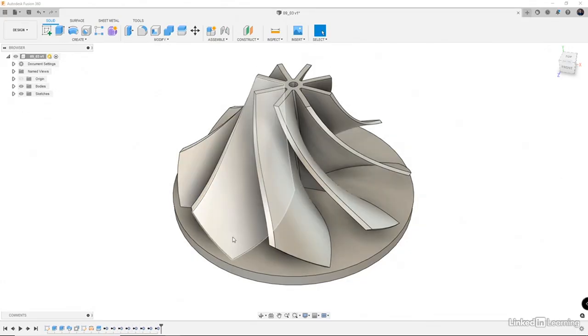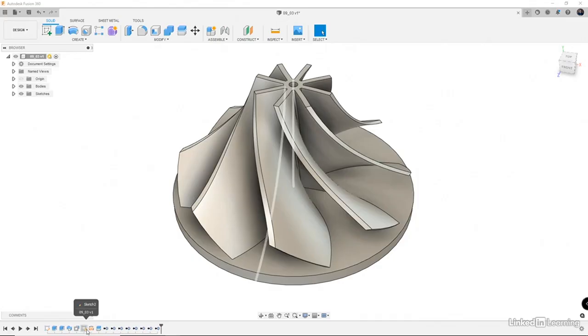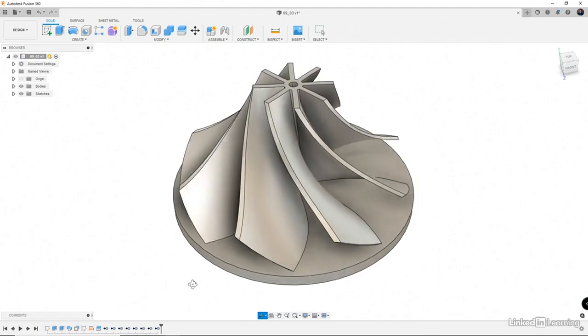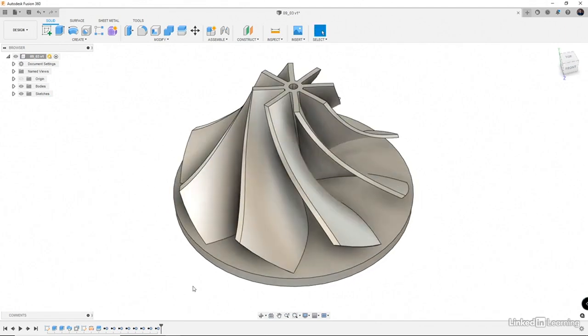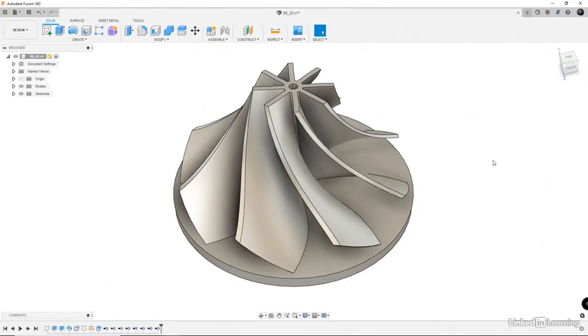And that's it. So within one sketch, two extrudes, a sweep, an offset, another sketch, a revolve, a split, and a couple removes, we were able to build this geometry. So just things to keep in mind, how you can use sketching to drive some pretty cool complex bodies.